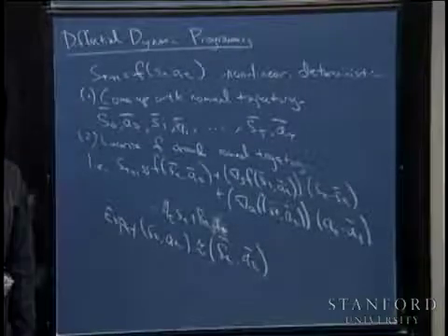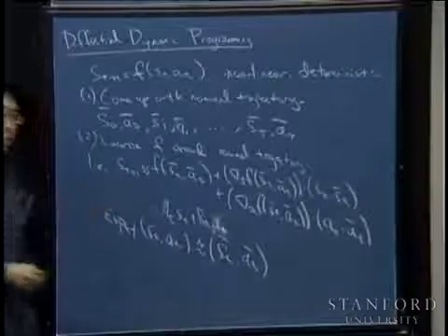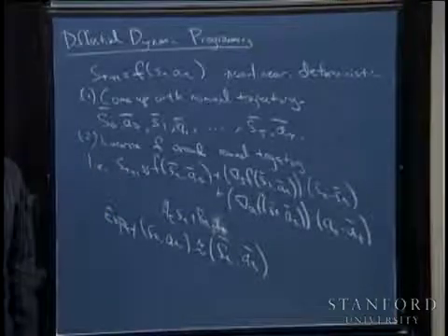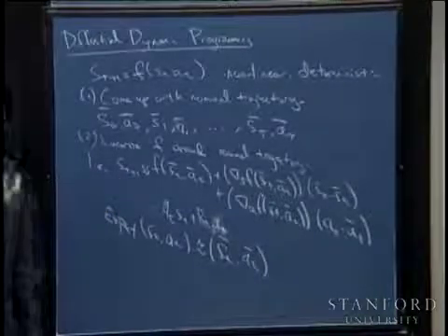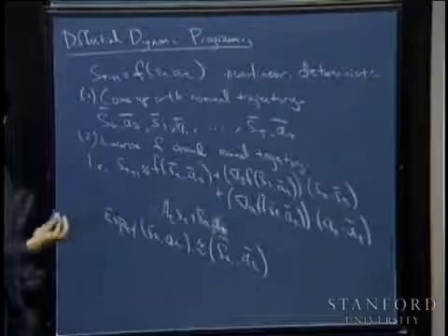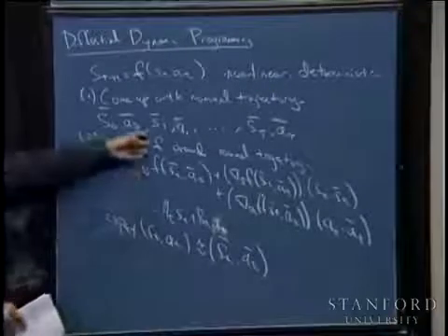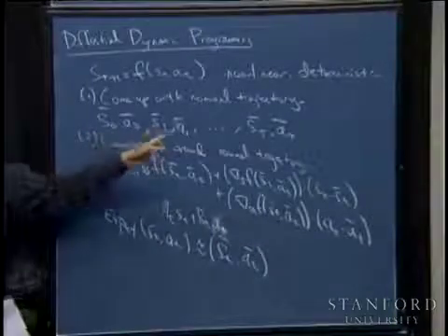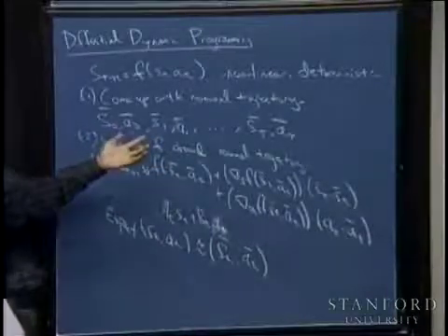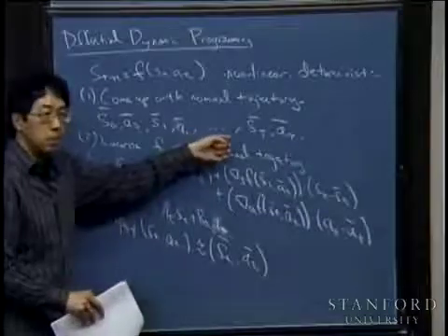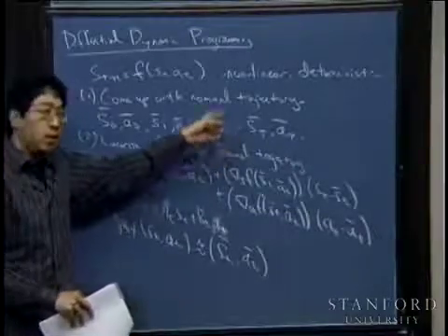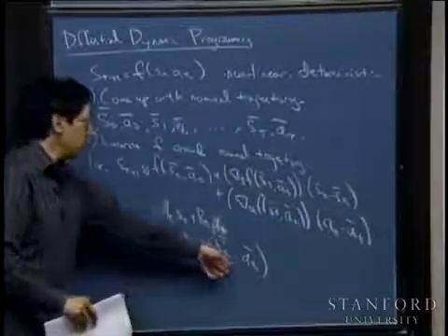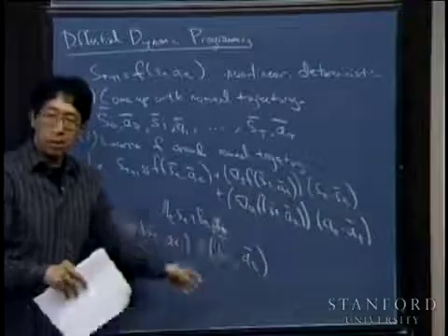So you want to fly a trajectory, maybe you want to make a 90-degree turn. Maybe you have a bad controller that does a pretty sloppy job, but at any given time, you're still moving along this trajectory. And so this is really telling you, very roughly, where along the 90-degree turn trajectory do you expect to be at any given time. And so let's linearize around that point. Okay.